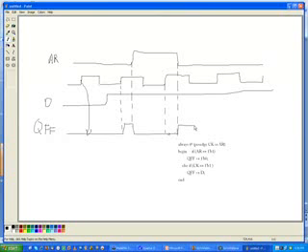So what's the problem with that? Well, the problem is that it doesn't accurately model the flip-flop, because it doesn't clock based on this going low. It shouldn't set the Q flip-flop back high. It should only do it on the next clock edge. So in real life, this should stay low until we get our next clock edge, and this is where it should go high. So it doesn't accurately model. This is one case where it can't accurately model, so be very careful in what you're writing.